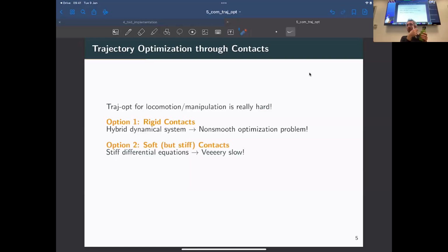If you tune the stiffness of the contact model to a very large value, such as 10 to the power of 5, the behavior you're going to see is very similar to the naked eye to the simulation with a perfectly stiff contact model. So that would be a reasonable approximation.